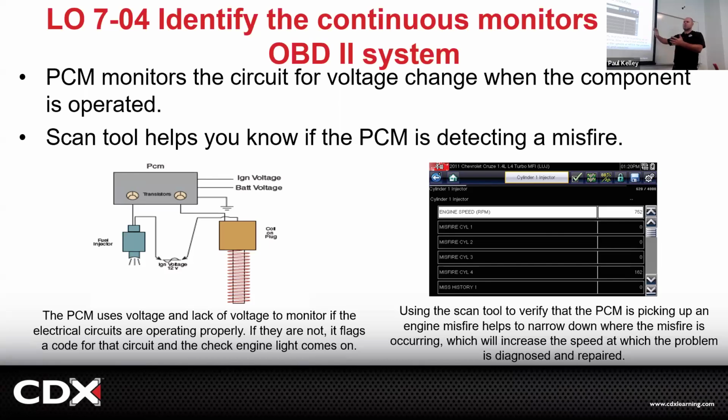So we're not really looking at 2, 3, 4, 6, 7, and 8. And we're not really looking at the O2 sensor. We're like, hey, it's in the injector circuit, but we don't necessarily know that it's the injector. See what I'm saying? So if I would reword that, it'd be like this. You're looking for somebody's house. The onboard diagnostic system setting a code will tell you that it's in the United States, that it's in California, maybe even potentially the zip code. Then after that, it's up to you to test the system and check the streets and actually physically locate the house. The onboard diagnostic system doesn't give you the whole address.